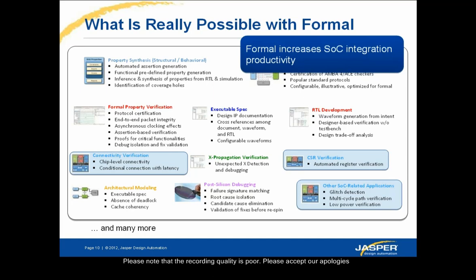And on the SoC front, that's a fairly rich area of applications for formal that lie outside the general area in which it's been deployed in the past. So one area that's getting a lot of focus at the moment is an application for low power verification. So using UPF to verify that the low power intent of your design is actually going to still work when the UPF is installed. And there are other areas in the SoC domain that we're investigating.